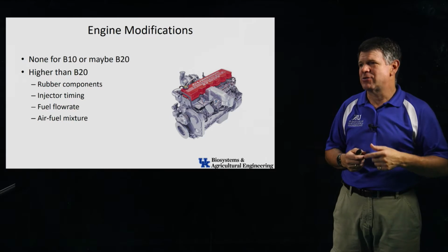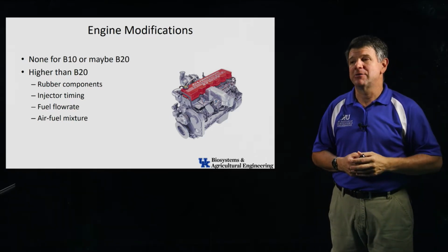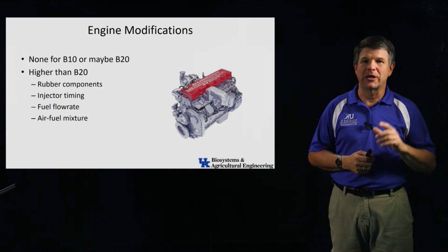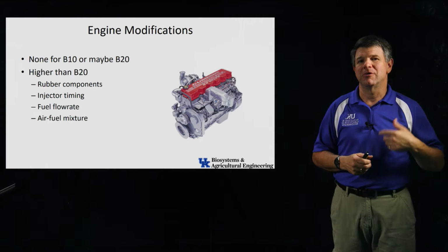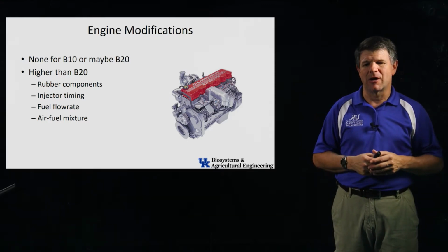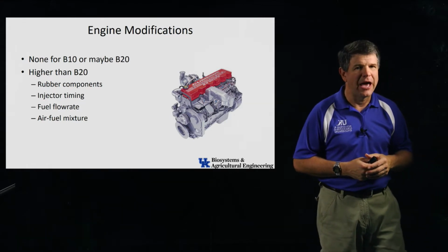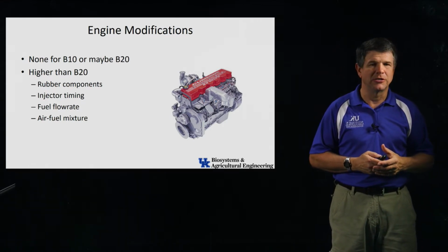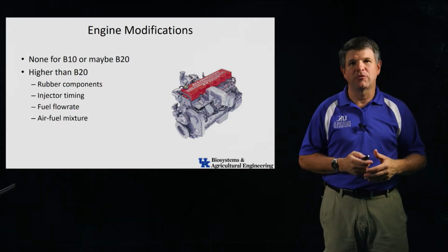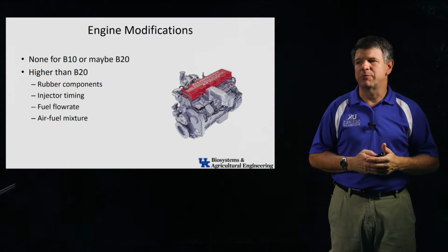But again, manufacturers will adjust the timing and things like that on the fuel. So can I put biodiesel in my engine? Yep. Watch carefully the hoses and all that kind of stuff, and you may have to replace them with some synthetic. Most of the engines now are manufactured with a Viton or some other synthetic rubber material that isn't affected by biodiesel, so they can handle the higher concentrations of biodiesel. But if you get above 20%, then you've got to really think about it. Anything less than 20, you can pretty much put it in and go with.